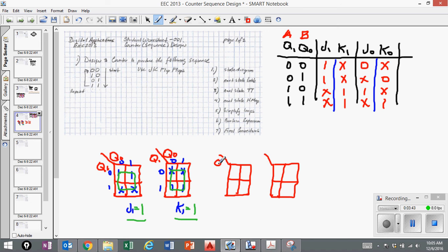Remember, we're taking our inputs from the current value of the flip-flop that will drive the combinational network so that the proper values of J and K will be available for the next state. These are all pretty routine processes. Doesn't require a lot of thinking once you practice.